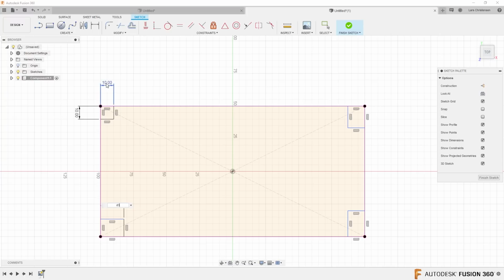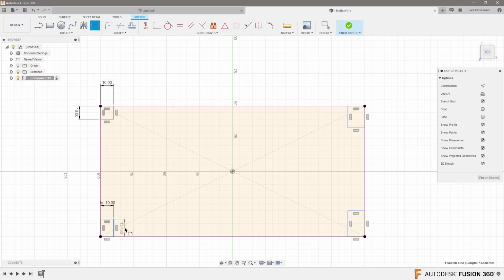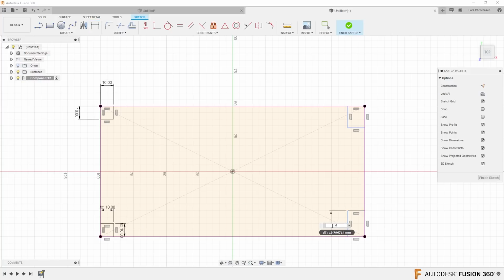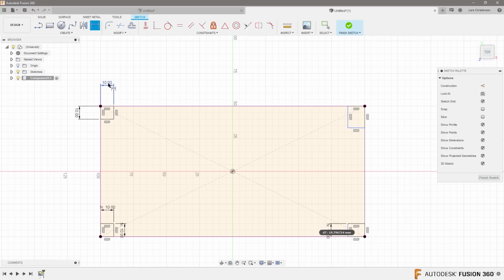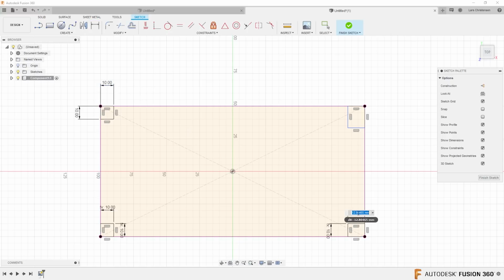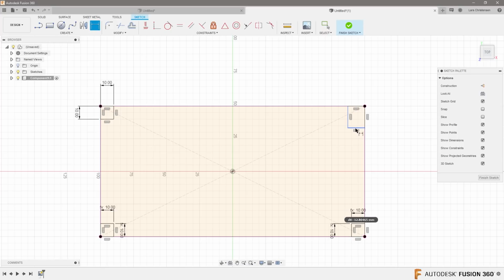And then I can actually just click on this. So you see that's D3. I can click here, place that, D3. Click here, D3. So I'm actually just copying this 110 up here into the rest of them. So now if I change the D3 dimension, everything will update.